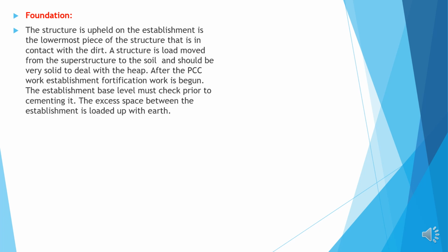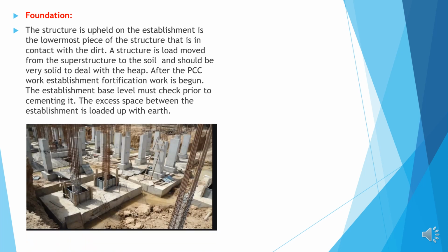After the PCC, foundation reinforcement work has to begin. The foundation base level must be checked prior to concreting it. The excess space between the foundations is filled up with the earth. See, this is the image of how to carry out the foundation works.